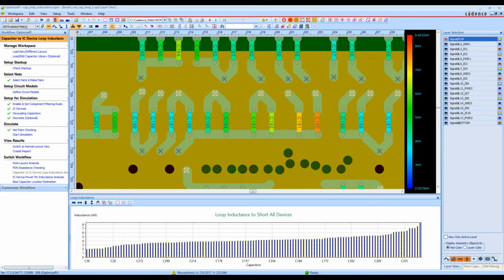Okay, and it looks like on that point of setup, there's a question here: is this a post-layout analysis only, or is there pre-layout planning available as well, such as the ones for SI tools? Sure, good question. We did show one pre-layout example where we had a component and wanted to determine where it would be a good idea to put decoupling capacitors around it. So you can determine where those decoupling capacitors should go pre-layout, so you can make a good layout choice and put them in a good spot. We definitely have some pre-layout tools available to help you as well.